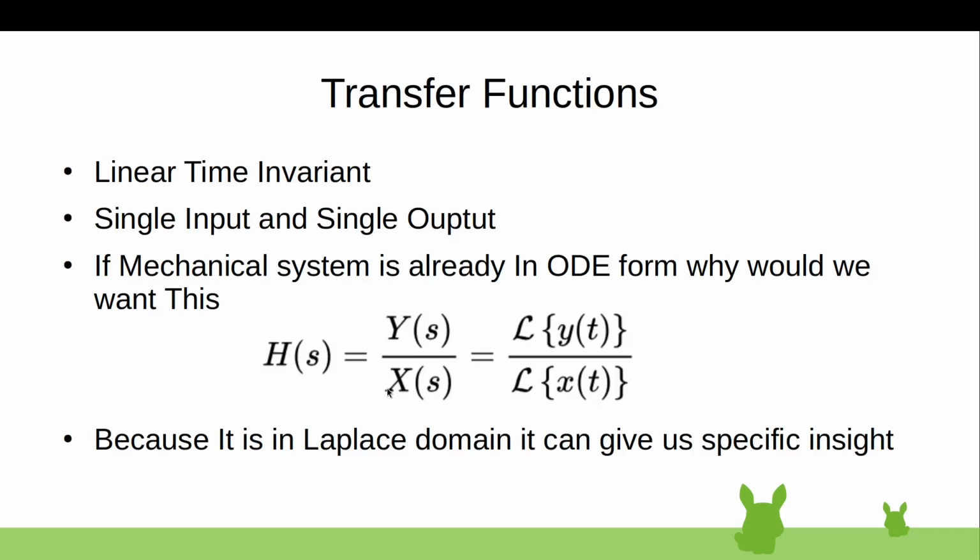Intuitively, you can tell what is going on from what I said before about integration. So double integration is going on, right? You can kind of tell, but you don't get it exactly. That's because when you operate a transfer function, you give it an input. So what would be the input of 1 over m s squared? That's right, it's the force. And how does it work here? In transfer functions, you just multiply your input onto the transfer function.